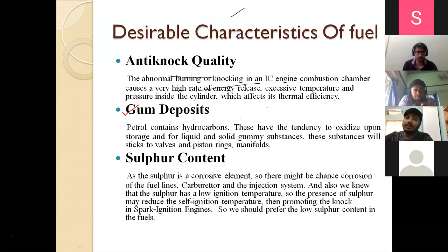Next is gum deposit. What is gum deposit? Fuels are hydrocarbons, and because of their chemical properties they have a tendency to oxidize in storage and form liquid or solid gummy substances which may clog the intake manifolds, the exhaust manifolds or the piston rings.